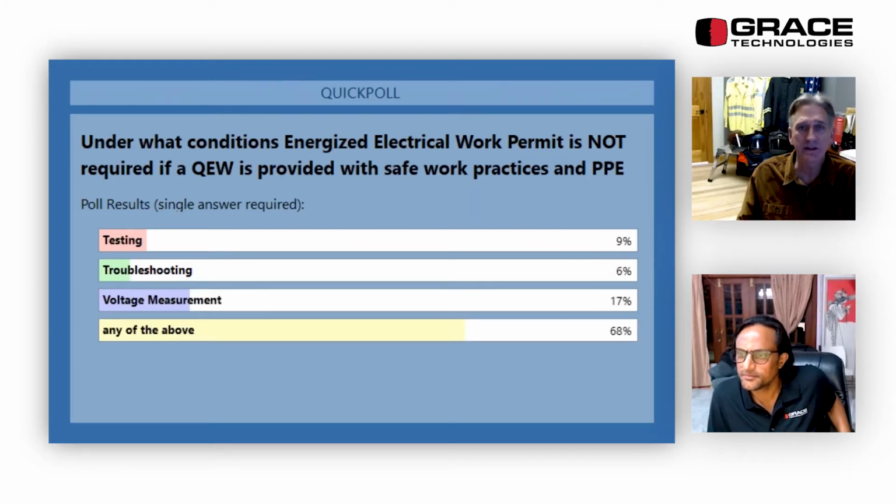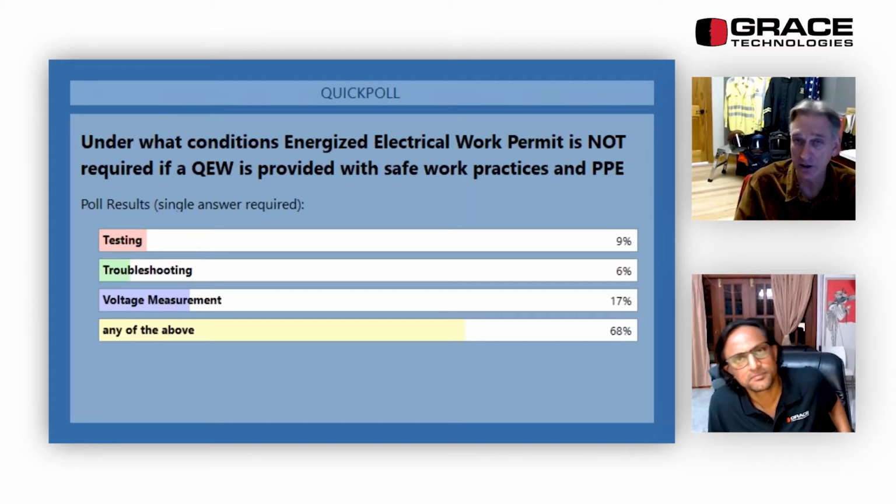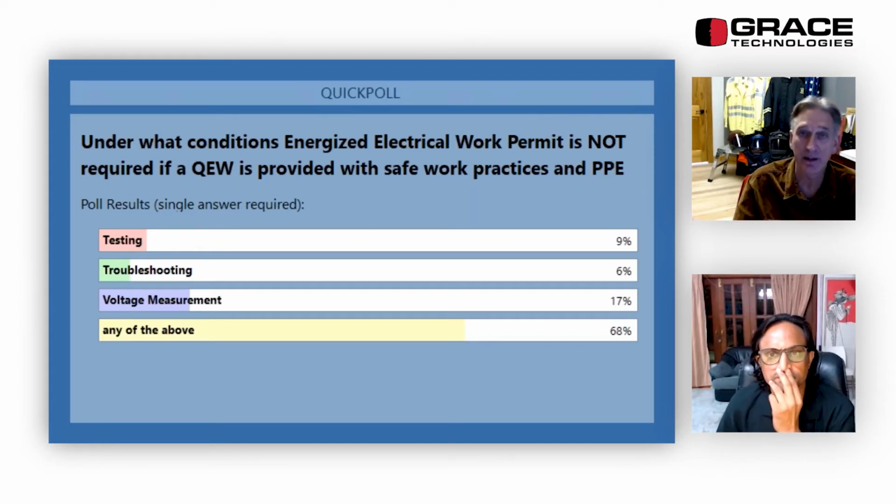And here's one thing that a lot of electricians and maintenance people don't think about. You've got a disconnect switch right at a pump, and one of the fuses blows. And so the electrician or maintenance person goes over there, maybe they suit up, hopefully they suit up, they open it up, they test, they know that there is a fuse that's been blown.